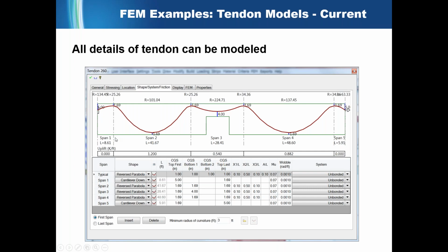And here, for example, you have a section, this looks like a slab or beam section without supports, but there's a notch in the center of this slab here. If you're using some other solution, it might be difficult to see where your CG point is referencing. And so here it's very, very clear. You can see exactly what you're referencing off of, what point of the slab is 4 inches away from your PT. And so that's really important, that you have that transparency.